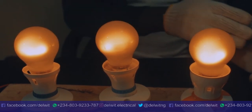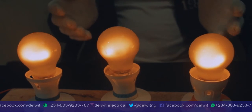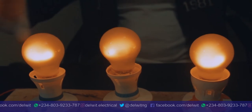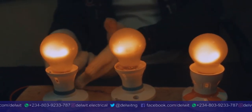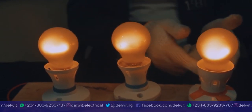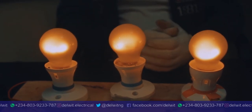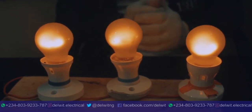Like in a parallel circuit, we're still going to do a connection in parallel. When we do a connection in parallel, you discover that the voltage here is equal to the voltage here and is equal to the voltage here, and they will all illuminate at 220 volts. But in series, by the time you measure this, you discover the voltage here is higher than the voltage here, which is higher than the voltage here. So I believe you've been able to understand how the series connection works, and this is exactly the practical aspect. All the calculations you are going to be doing in series follow the same principle. I believe this series resistor calculation has been very educative.